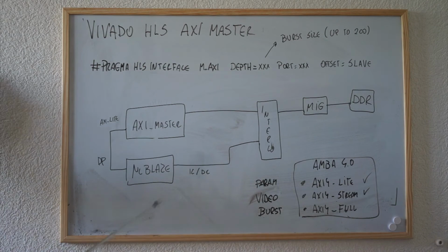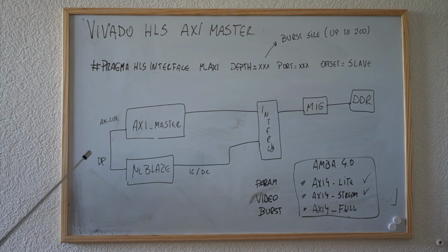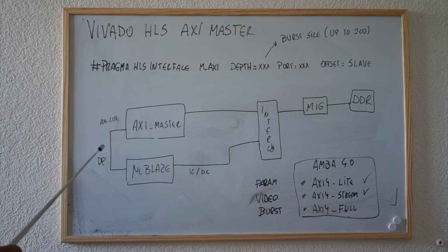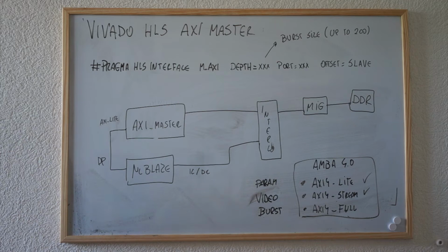We're going to create in the lab what is going to be an accelerated memset, so to speak, and it's going to have an AXI-Lite port to set up some parameters like the value that you want to memset, the address, and stuff like that. After you send the start command, it's going to initialize the DDR with some values. Now I'm going to switch to the lab, and it will be more clear what we want to do. Hope you guys enjoy it, and let's go.